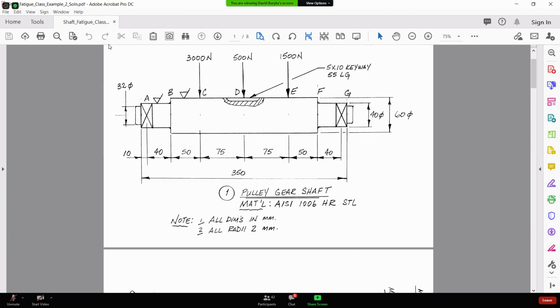The design equations that we talked about in the lecture, I think you're going to be using the Soderberg criteria for Sebastian's course. You'll have a torque component, and they just go into the formula and you stick it in there. He'll be giving you the stress concentration factors, which we'll talk about today, where he got them from.